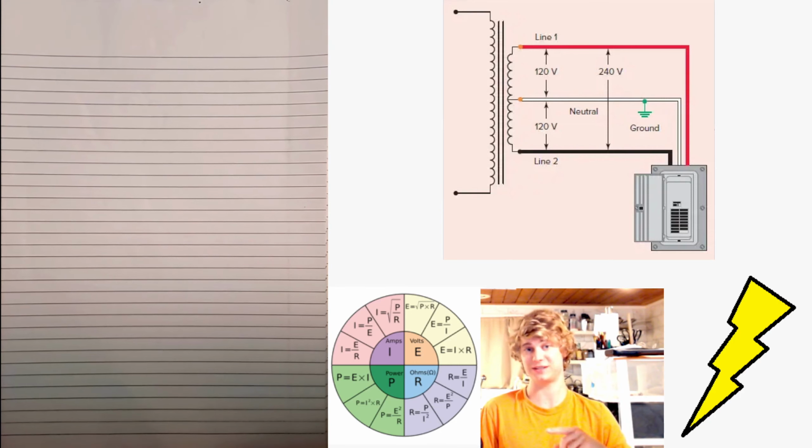There are two-phase systems, but that is very rare. You usually have single-phase and three-phase. So yes, two-phase does exist, but in no case are you going to have two-phase in a residential circumstance. When you have the single-phase system, like shown above, where on the secondary of the transformer, you have the two lines, 120 volts, and the neutral.